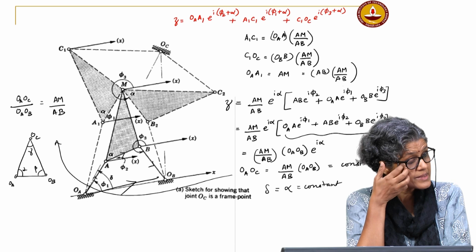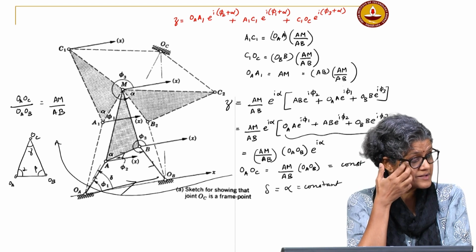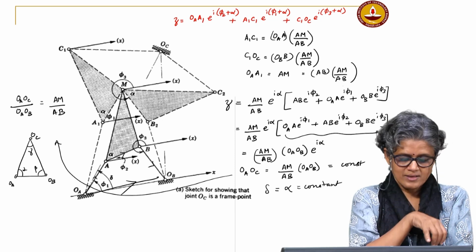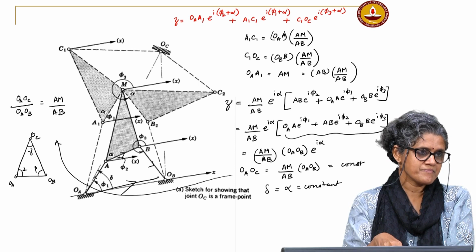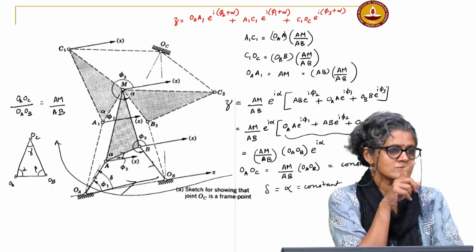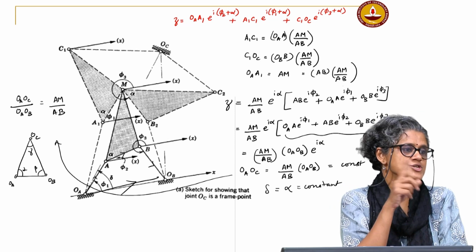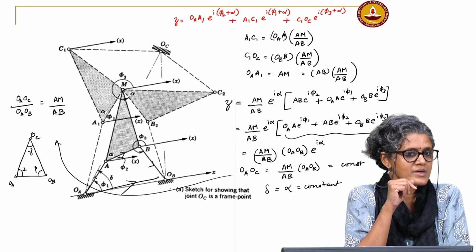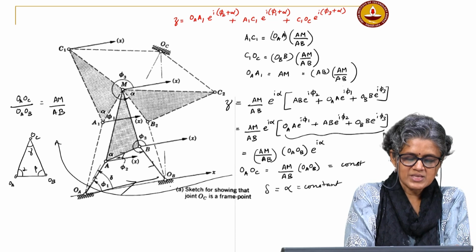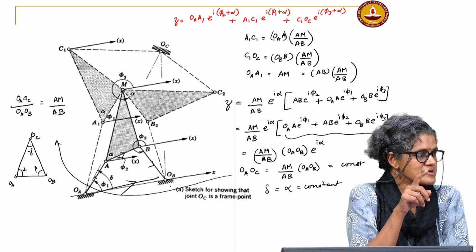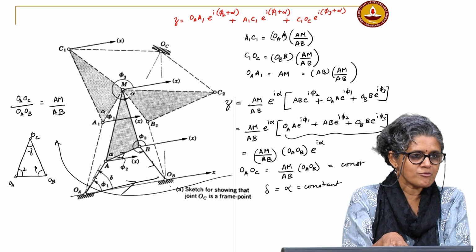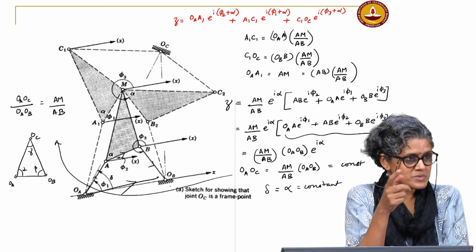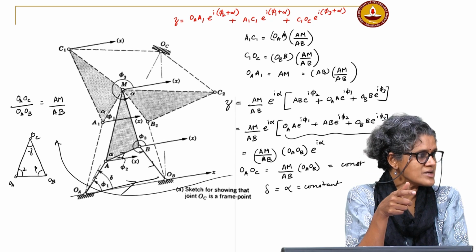So, you locate the third fixed pivot by constructing a triangle with base OA OB that is similar to the coupler triangle whose point motion you want to find. Okay. So, this is how you get the location of the third pivot. If you have the original 4 bar, you can find the location, and if that is more suitable, then you can look at using one of the coordinates.